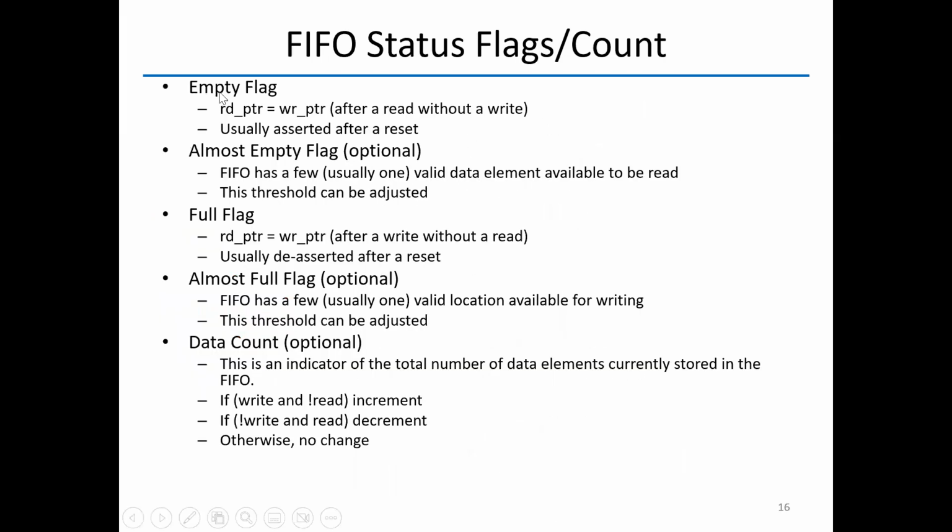We have empty flag. If read pointer and write pointer are pointing to the same thing, that means the next read will have nothing because they are on the same level. The next thing, it will be empty. So we'll get empty flag.